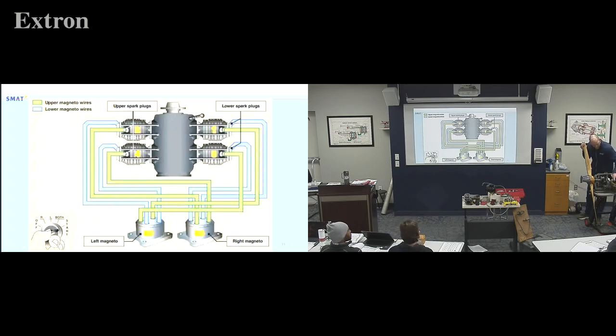So the idea is we've got valves that will open and close to the exhaust and inlet, but if I start this at the right point, I'm going to find my spot. Exhaust. Okay, so this valve on this side on this one is my inlet. So the first stroke of the Otto cycle, the inlet valve is open, so air from my manifold, which also has fuel in it, is being drawn into my cylinder. So that's the first stroke. We call that the intake stroke. So I'm going to back up in time and say my intake stroke, I'm drawing fuel and air into my cylinder. So that's the first stroke of the Otto.